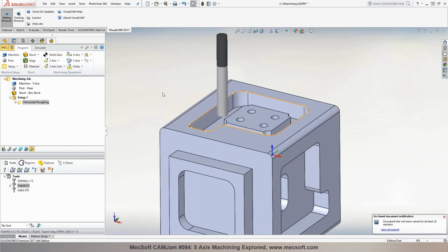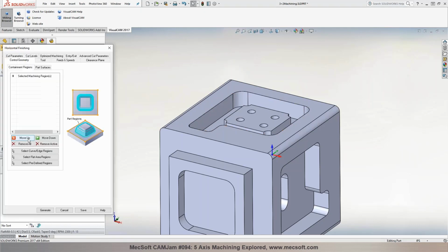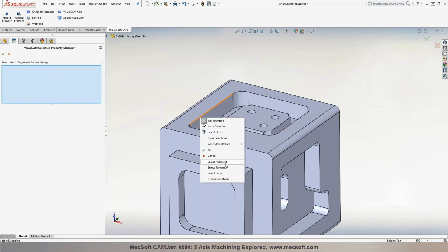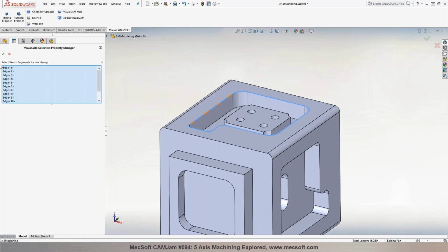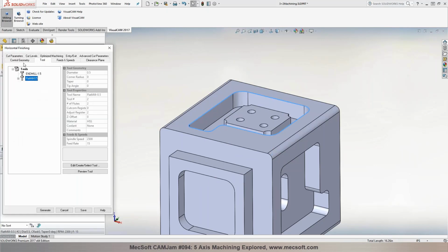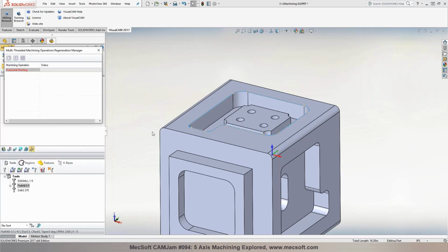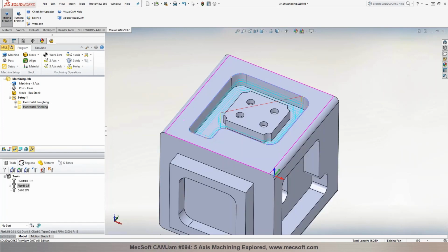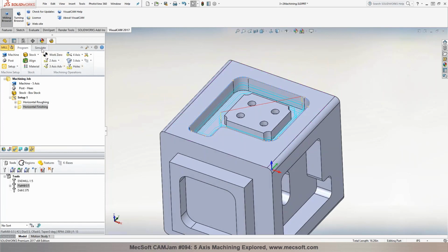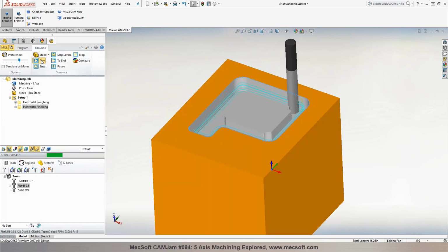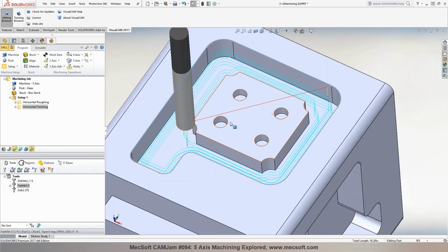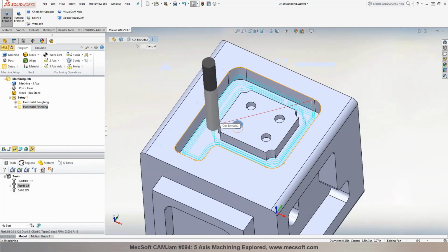And now you can go from a roughing operation to a finishing operation. You could program a horizontal finishing, or we could do a 2D pocketing, depending on the type of operation you'd like to program. You specify the cutting parameters in here, and you click on generate. So this would produce a finishing toolpath around those areas. Since you're familiar with how to program your toolpaths, I'm not going to spend a lot of time on this here. Again, if you want to do a pocket or drilling, you can drill or pocket these holes.